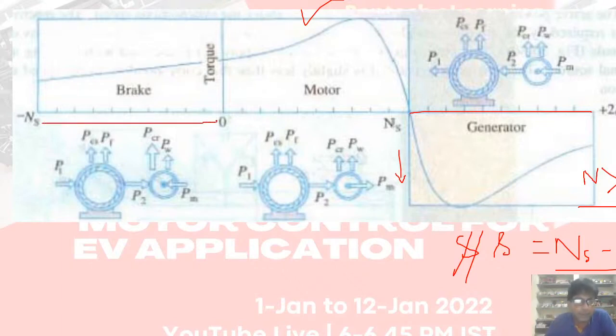You know, take our locomotives, first the electrical brake will apply, then the speed will slightly reduce, then the mechanical brake will apply. There will be a thruster brake or electromagnetic brake, with a brake shoe, which is spring operated.